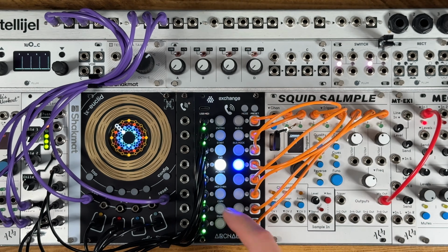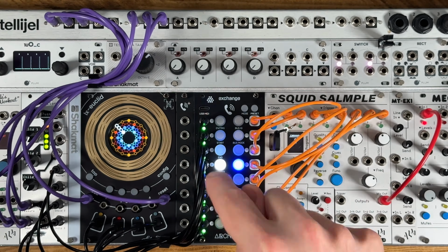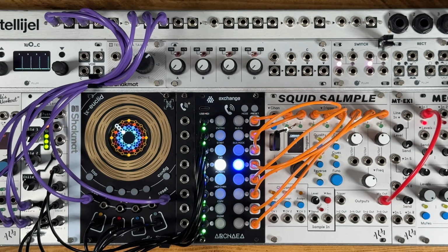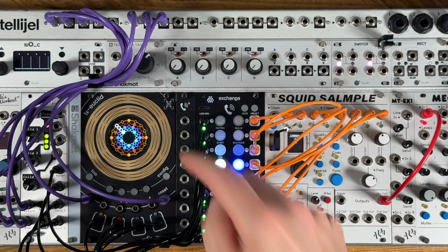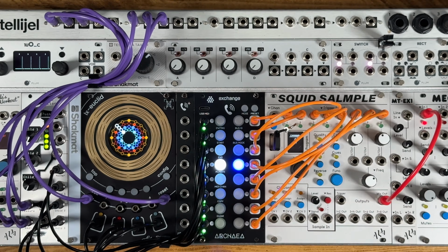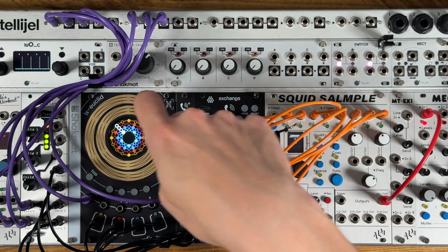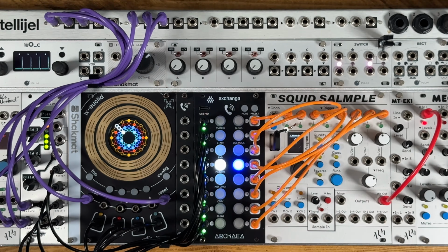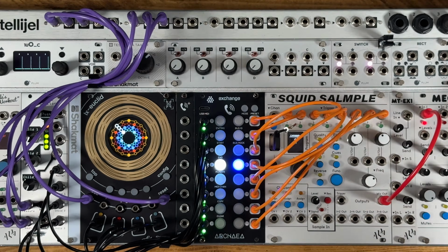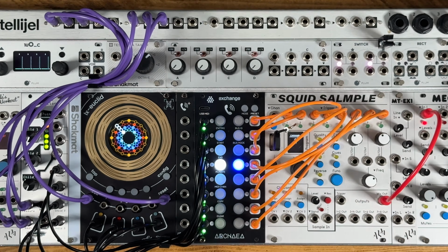If you're using it sequentially, then input 7 is a reset back to the first starting preset that you've defined. So if you're using all 8 inputs on the front panel, you can use inputs 7 and 8 on the expander to do the preset switching, or vice versa. You could connect your signal sources to the 8 inputs on the expander. And because these are connected via ribbon cables on the back, you could locate these a bit further away from the main Exchange unit. In a bigger case, this is really handy. You could maybe put an expander next to your trigger sequences and have Exchange a bit further away, and you can likewise have an expander on the outputs which are a bit closer to your drum modules, and then you can spread things out in the case a bit.